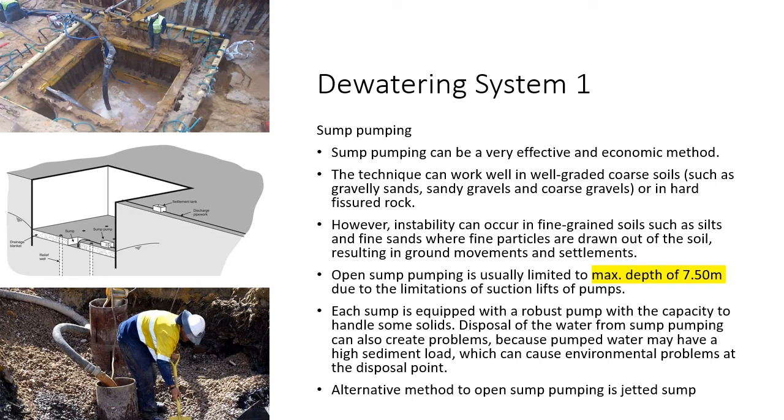Disposal of water from sump pumping can also create problems because pumped water may have a high sediment load which can cause environmental problems at a disposal point. Alternative method to sump pumping is jetted pump.